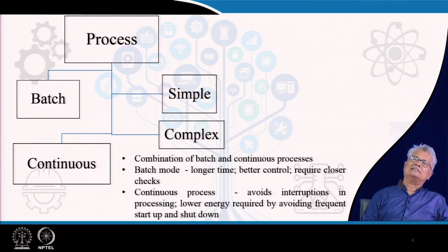The first thing, since the entire batch feed has to be held in the same equipment as the batch starts, the batch equipment for the same capacity per day will be much larger in size. In case of continuous plant, for example, if I am processing 10 tons per day, the capacity of processing will be 10 divided by 24 hours, roughly slightly less than 0.5 tons per hour. So, quite naturally at a time I will be having a much smaller quantity of hold up in case of continuous equipment, and my process equipment size is going to be much smaller.